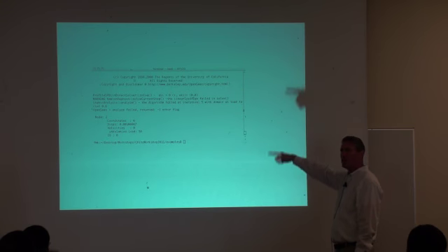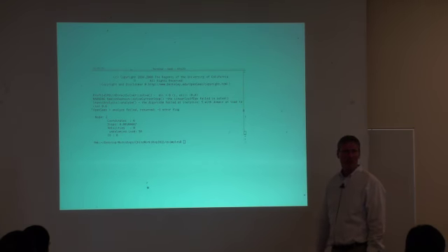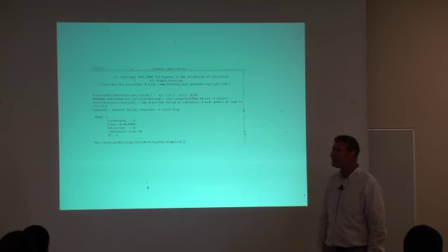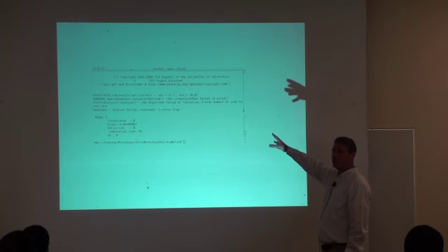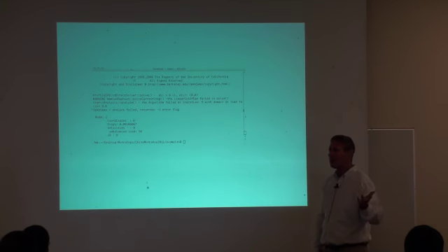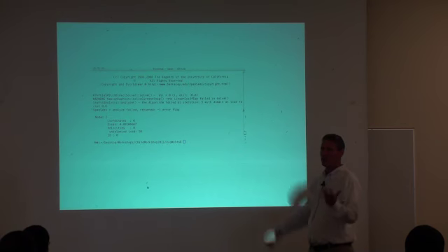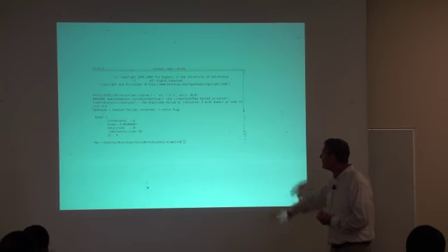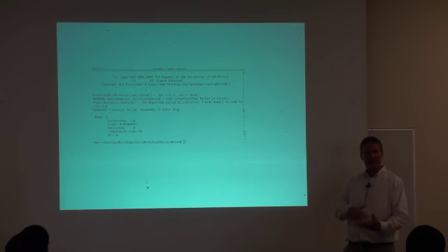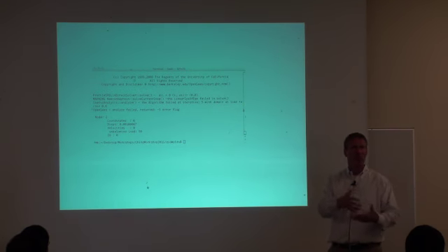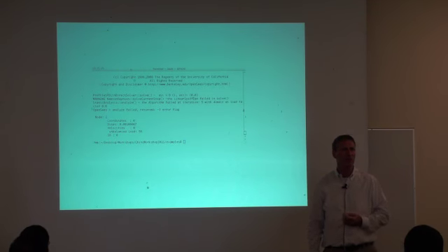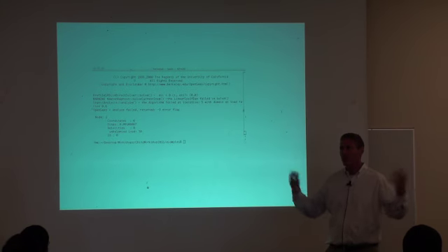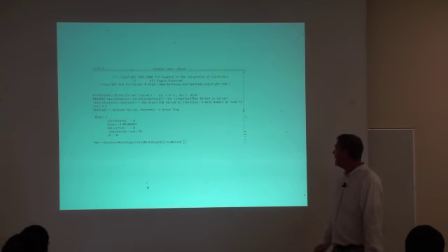OpenSees is going to come out with stuff like this, and this is stuff you have to understand if you're going to be doing nonlinear analysis. What this is basically saying is that because I was using the profile solver, it actually failed because the matrix is no longer symmetric positive definite. So A(i,i) is less than 0. That means the diagonal entry in the matrix is less than 0, so it's no longer symmetric positive definite, and we're using a symmetric positive definite solver, profile SPD. So the solver fails, and the analysis fails.